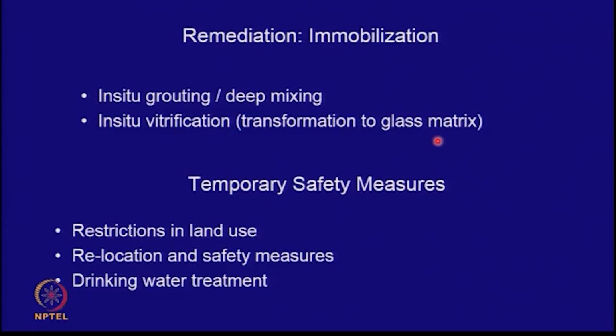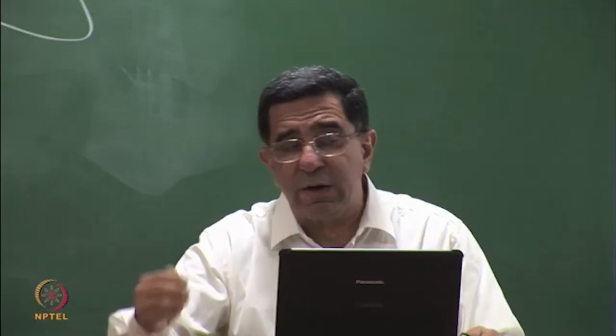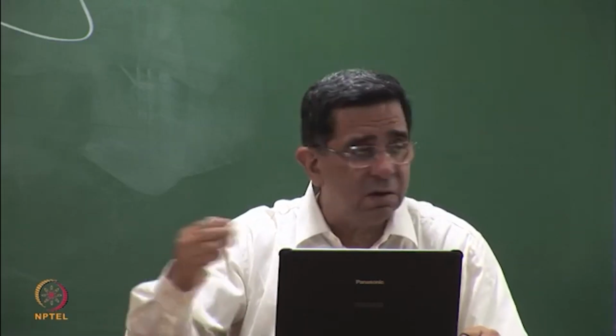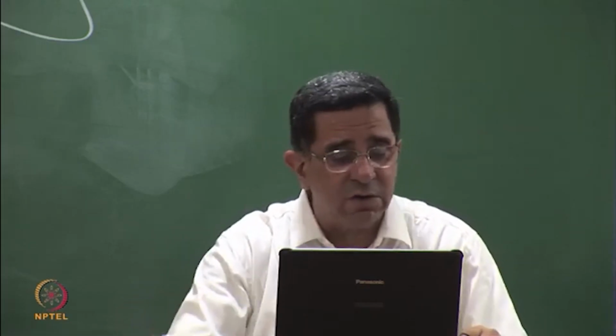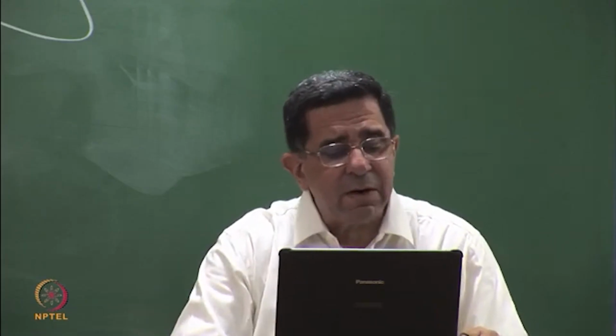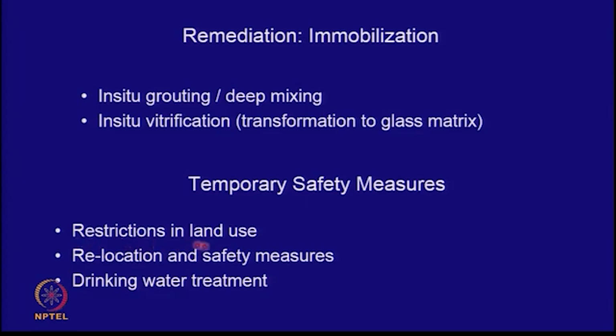So these are some of the remediation techniques which are adopted, for which you will have to use the appropriate engineer, whether it's a chemical engineer or a thermal engineer or a biochemical engineer or a chemistry expert. But temporary safety measures while we are doing all this are restrictions in land use, relocation of the people and adopting safety measures, and of course drinking water treatment and actually closing all the groundwater wells from which this material is coming out.